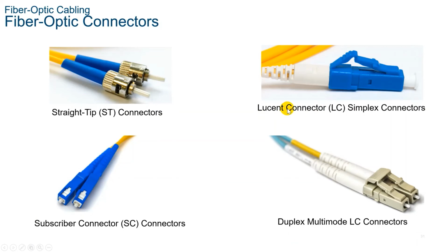so until recently, light could only travel in one direction over the optical fiber. So two fibers were required to support the full duplex operation. So therefore, fiber optic patch cables bundle together two optical fiber cables and terminate them with a pair of standard single fiber connectors.